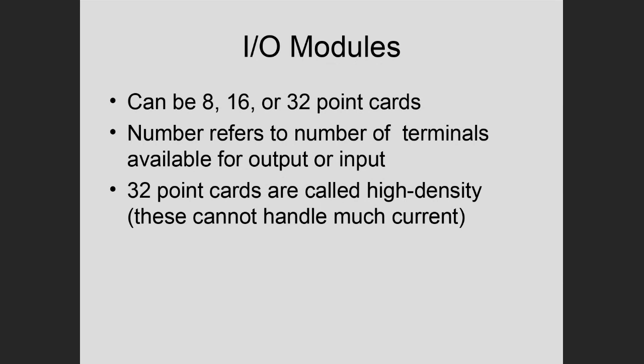They're different depending on if you look at, for instance, Allen Bradley, the one I just showed you, the PLC 5. The simulation software you're going to use is based on the Allen Bradley. They call it SLC 500. So it's pretty close to this, just a little bit different. But if you get one from Siemens, their format will be completely different. It'll work the same way, going from wide to small, but once you understand any of the PLC addressing formats, the learning curve to any other manufacturer is small. Once you understand one, you'll understand them all. They'll be just a little different.